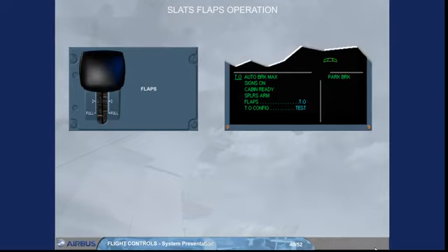As soon as a flaps lever selection is made, the engine warning display will display the following changes: a blue number, indicating which flaps lever position has been selected. Here, it is 1 plus F, because the speed is less than 100 knots. Blue markers, showing the selected flap and slat positions. The white labels S and F, and the current slat position green marker will move, followed by the flap green marker.